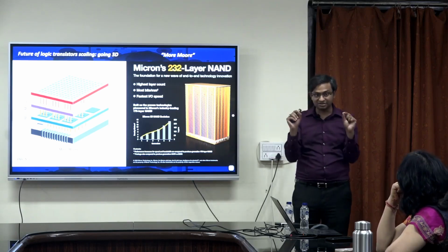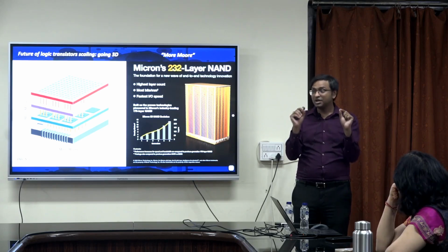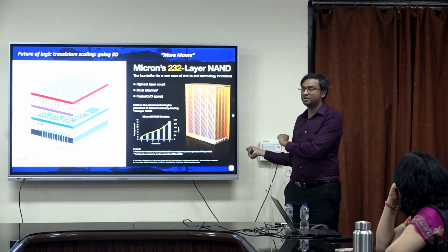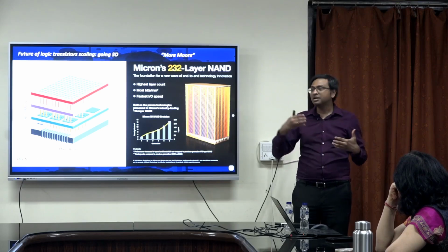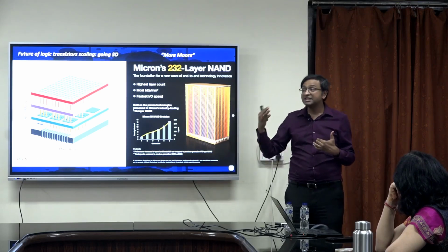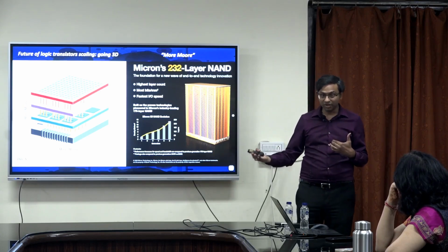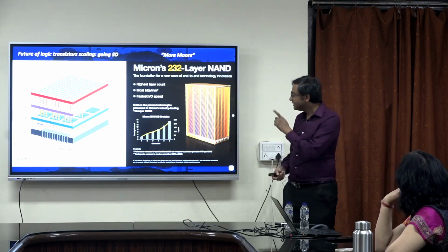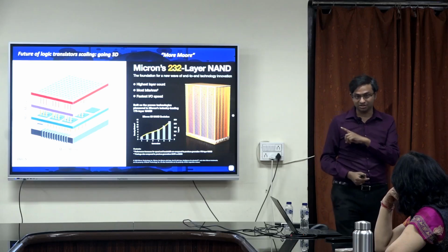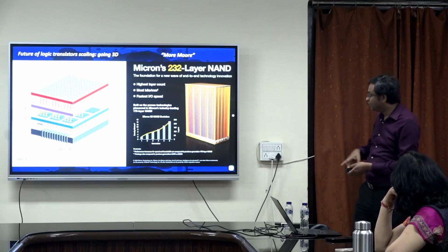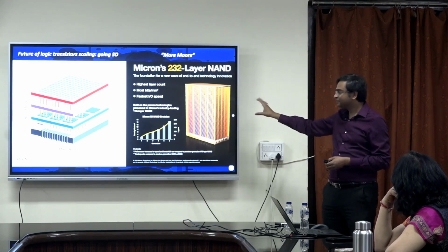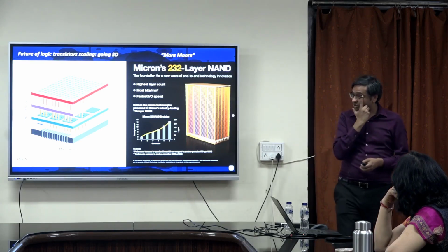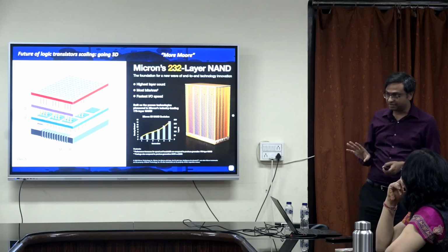I could use polycrystalline silicon as the channel of a flash memory device, because for memory it is the storage which is important, and for logic it is the performance. So, for logic you need really high quality silicon. Here you do not need really very high quality silicon, right. So, you could build these tiers for memory, while you could not do it for logic. This part is clear, right.